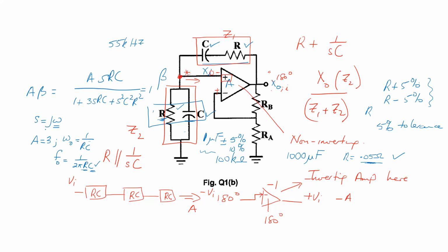Looking at this, and from experience, 55 kilohertz is relatively high, which means the two things below here have to be kind of small. So the product of R and C has to be small so that F0 is on the high side. You pick a small capacitor, just as a rule of thumb. A small capacitor, 1, you could even get away with 0.1 microfarad, that's good. So 0.1, 1, 0.5, those kind of values. 10 might be a little bit too high.